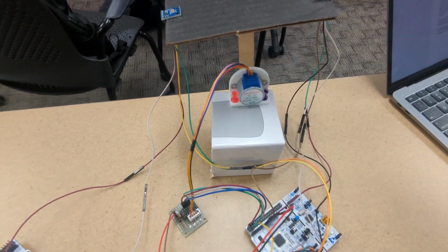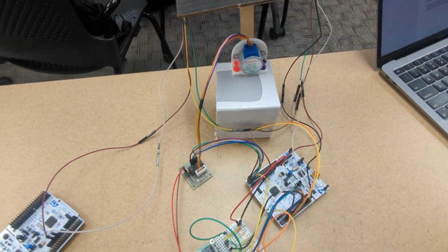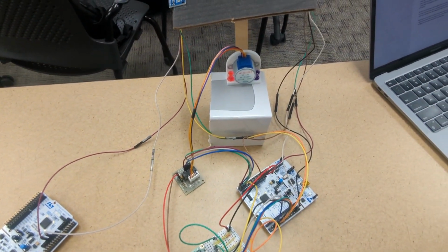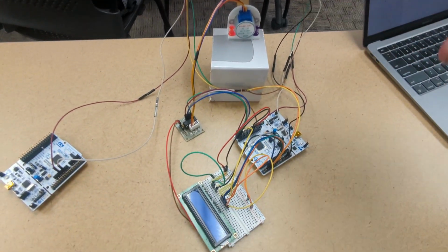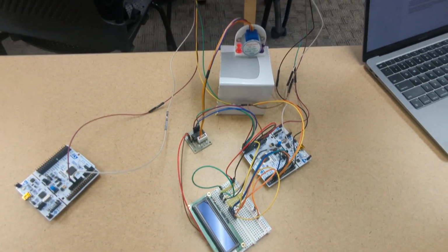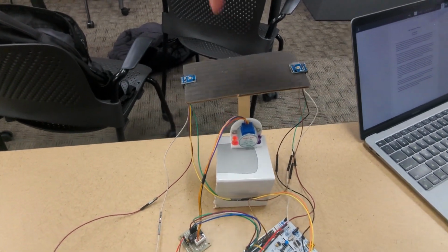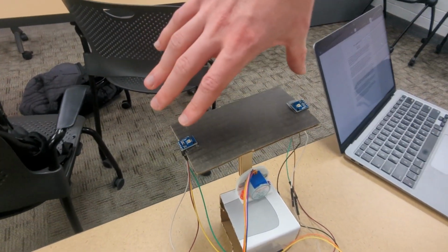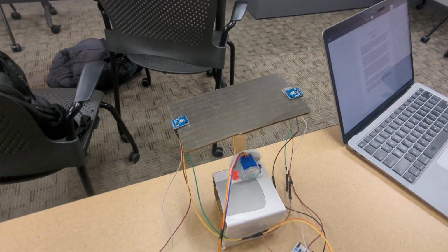This motor stand right here, we were able to 3D print with also a little gear on the back side that is able to tilt the motor. And then this stand we just made to prop up the thing. But that's basically all the hardware and how it works. Once the sensor is received, the panel activates the motor and then tilts the direction it needs in order to put the light in the center and make sure that these two sensors are reading a lux value that's within a 1,000 lux threshold.